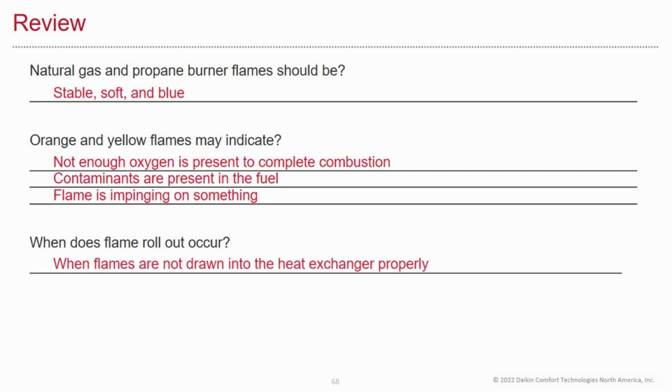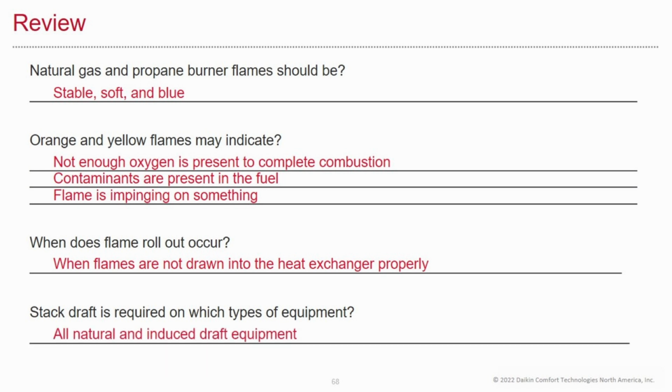When flames are not drawn into the heat exchanger properly. Stack draft is required on which type of equipment? All natural and induced draft equipment.